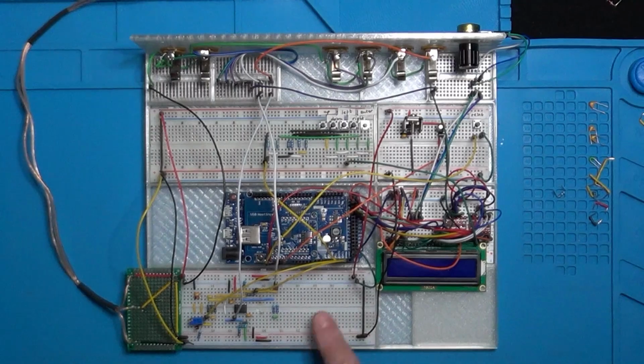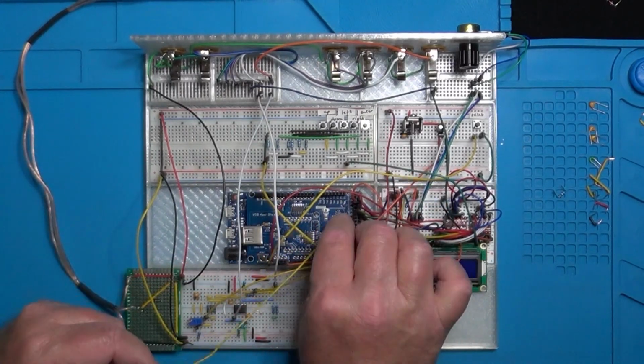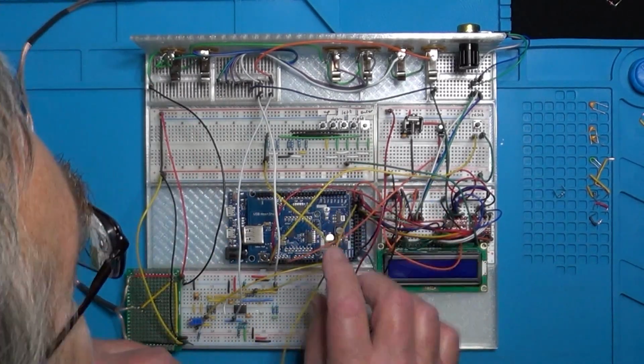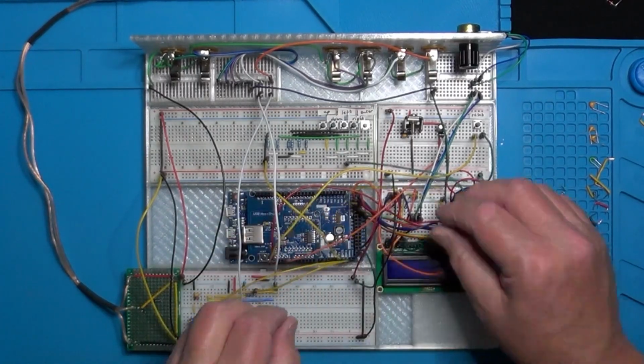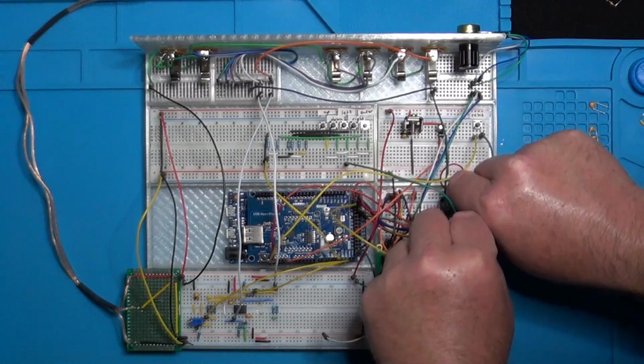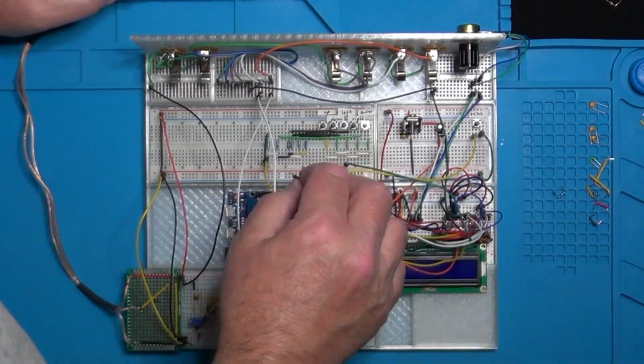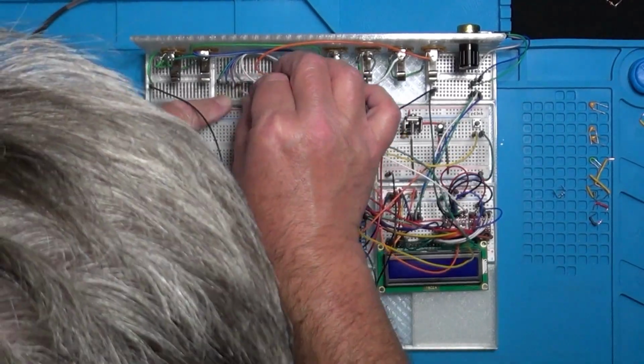Removing all those elements from the breadboard leaves a lot of available space for adding the control change circuitry later on. At this point, we need to connect the data pin 26 on the Arduino Due to the input of the last logic level converter, and the output of the same logic converter to the trigger signal jack socket.